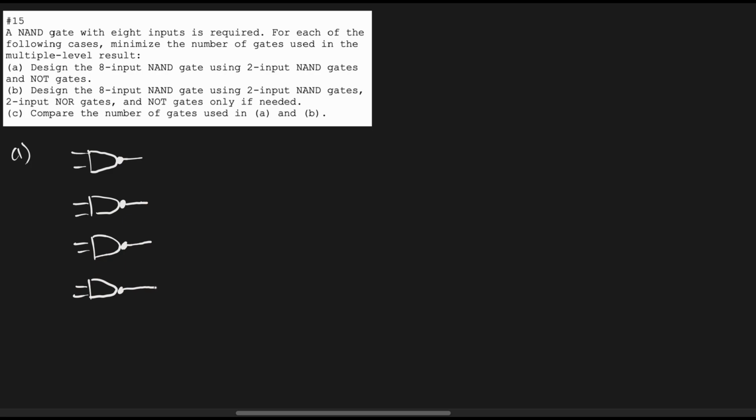Now we're going to use 2 input NAND gates, but we're also going to use NOT gates. And to do this, we can put NOT gates like this. However, I'm going to show the actual thought behind this. If we have NAND gates, we know the output of a NAND gate is going to be 1, 1, 1, 0, and we have 4 of these. But I'm just going to make 2. So we have 1, 1, 1, 0, and then this is our NAND, right? And we're doing this 4 times, so we'll just times this by 2.